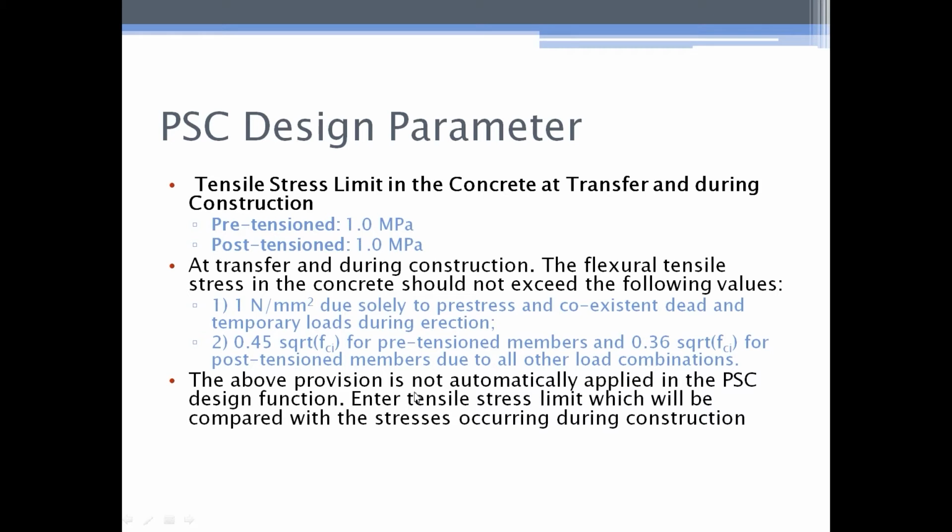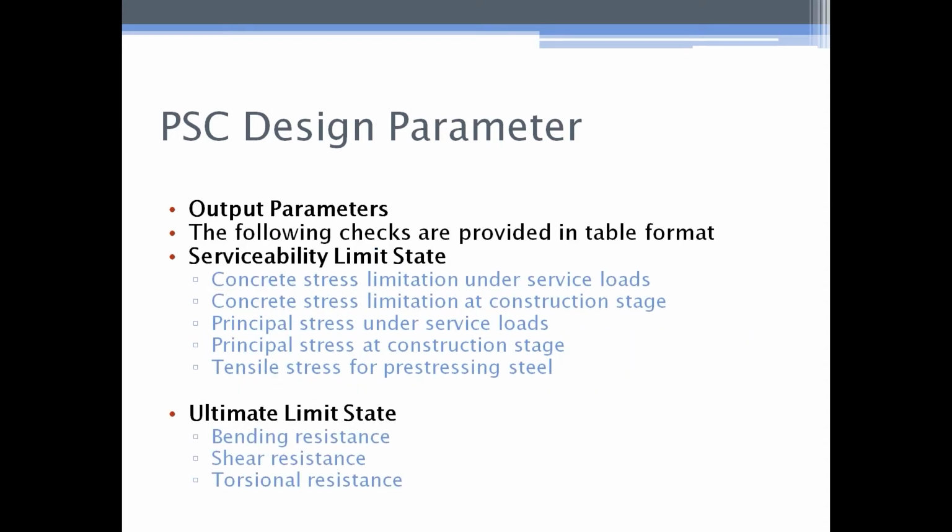The allowable stress will be input in the PSC design function in the Midas and will be compared with the stresses occurred during construction. The PSC design, again, we are still in PSC. The following outputs will be checked.